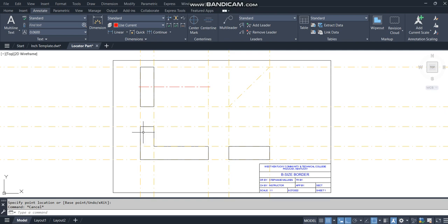The cut in the back is 1/4 inch. I can use offset, not have to use projection. I can use offset of this line 1/4 inch to place that in the top. So I don't always have to copy. I can use offset to create that. And it offsets into the part 1/2 inch on each side. So it comes in like this. While I'm in there, I would go ahead and trim to what looks like that part. So again, I was creating these cuts on the back edge. While I've got those marked, I can go ahead and trim that.